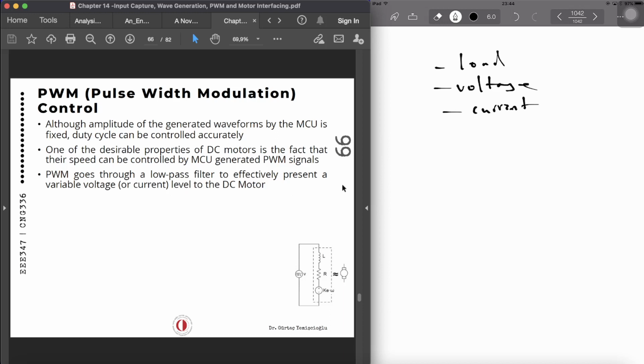For microcontrollers with PWM circuitry embedded in, all we have to do is load the proper registers with the values of the high and low portions of the desired pulse, which is the duty cycle, and the rest is taken care of by the microcontroller. It's quite easy, actually. And this allows the microcontroller to do other things at the same time. So it's giving us flexibility and opportunities.